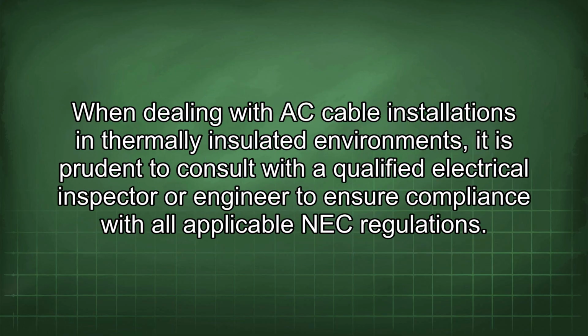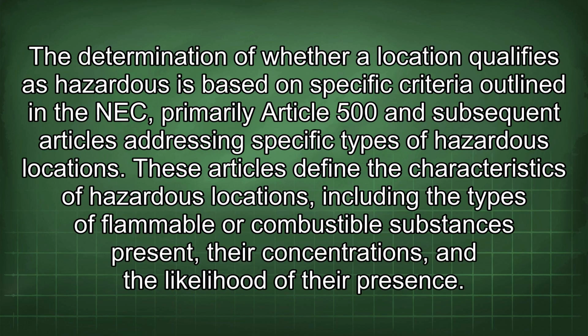When dealing with AC cable installations in thermally insulated environments, it is prudent to consult with a qualified electrical inspector or engineer to ensure compliance with all applicable NEC regulations. The determination of whether a location qualifies as hazardous is based on specific criteria outlined in the NEC, primarily Article 500 and subsequent articles addressing specific types of hazardous locations. These articles define the characteristics of hazardous locations, including the types of flammable or combustible substances present, their concentrations, and the likelihood of their presence.